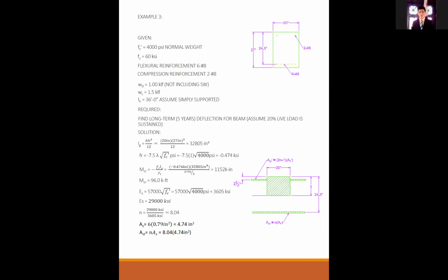In homework number 4, problem number 2, you are looking at the ultimate state. The concrete is at 0.003, the beam is massively cracked, and what you're solving for is little a. It is the neutral axis, sort of.